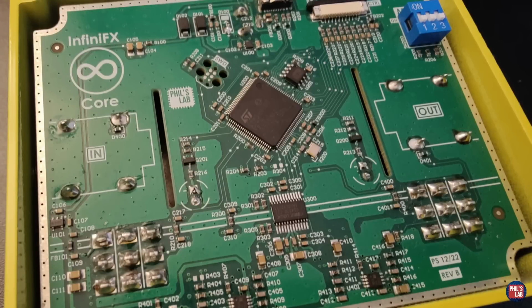And what we'll do, as we saw at the start of this video, is implement this on an STM32 H7 microcontroller-based guitar processing platform. I have a single mono input and a single mono output. I feed through some sort of analog filtering section into my ADC, which goes digitally into my STM32 H7, where we'll run the all-pass filter, and feeds out to the DAC through analog filtering into the output.